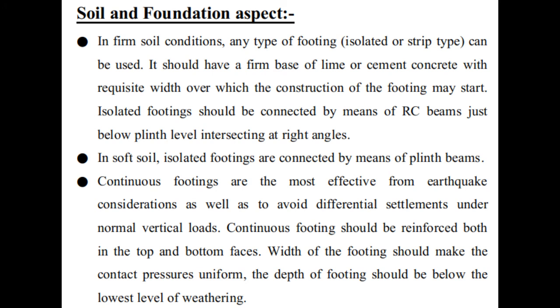Okay. In soft soil, isolated footings are connected by means of plinth beams. But continuous beams are the most effective from the earthquake consideration, because it avoids differential settlement under normal vertical loads. Continuous footing should be reinforced both in the top and the bottom faces. Width of the footing should make the contact pressures uniform. The depth of the footing should be below the lowest level of weathering.